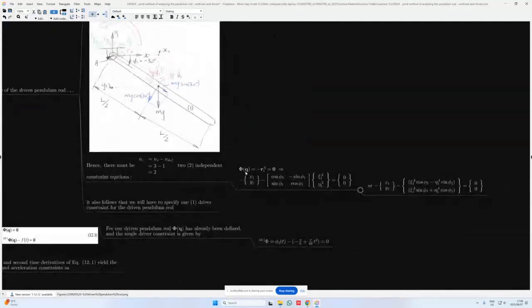And this is something that we also set up in the previous lecture, where we essentially looked at the constraint equation that we apply to the revolute joint. It applies to the x and y coordinates, and we just need to manipulate essentially this minus r1a vector in terms of its global center of mass coordinates, and then also some transformation matrix that is multiplied by the local coordinates of the point where the revolute joint is situated.